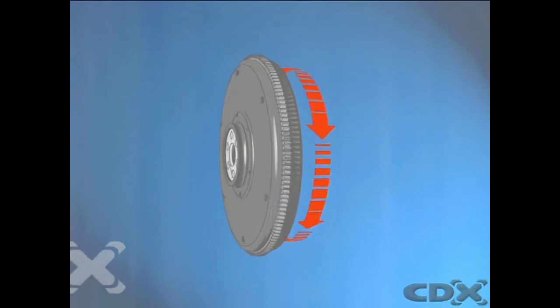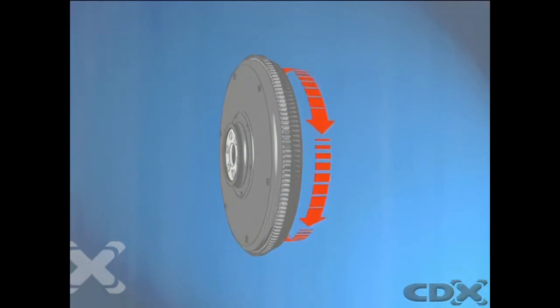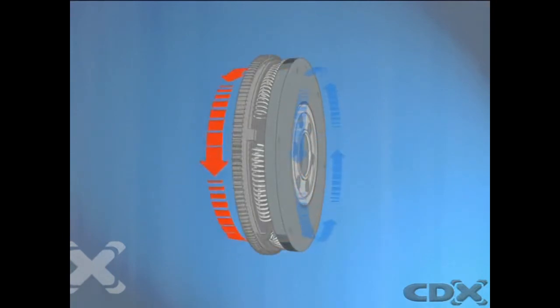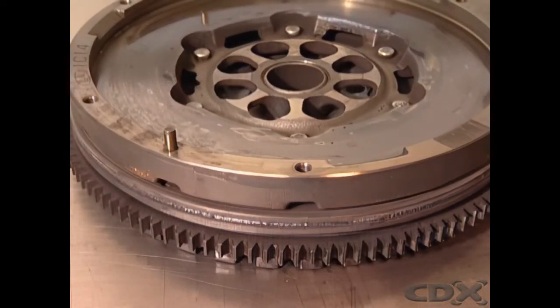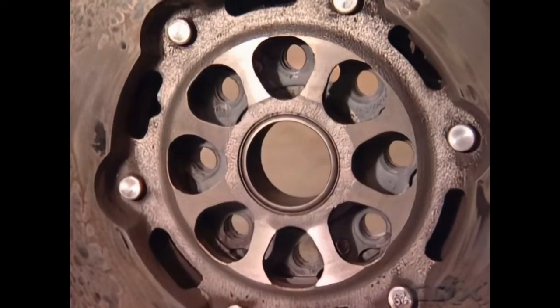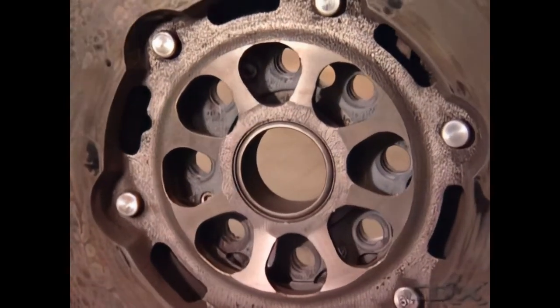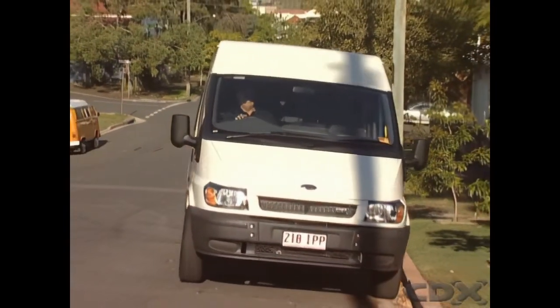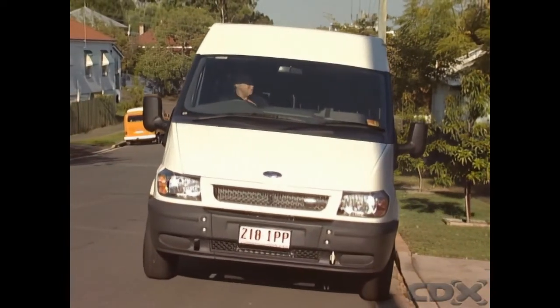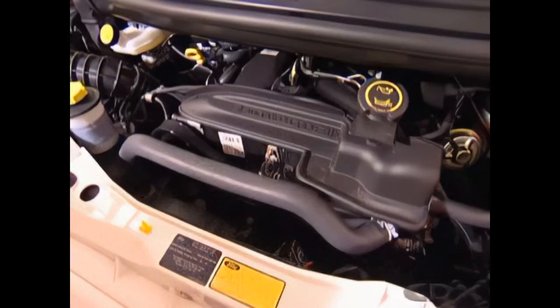If the dual mass flywheel was not used, the torsional frequencies could damage the transmission. The dual mass flywheel construction relocates the damper from the driven disc to the engine flywheel. This repositioning dampens engine torsional vibrations more than is possible with standard clutch disc dampening technology. Dual mass flywheels are designed to provide maximum isolation of the frequency below the engine's operating RPM, usually between 200 to 400 RPM. They're also most effective during engine startup and shutdown.